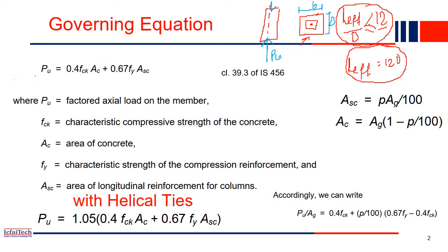You increase the load P gradually, and after some extent you will find there will be cracks in the column member. This failure happens because of crushing of material, not because of buckling, because we considered it a short column, meaning the length is low. If you gradually increase the compression load, after a certain point the column will fail, the material will crush at the center or anywhere. So let's consider this failure load as Pu.